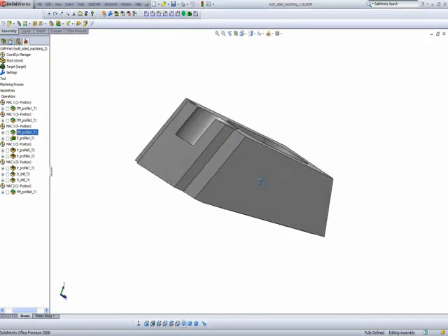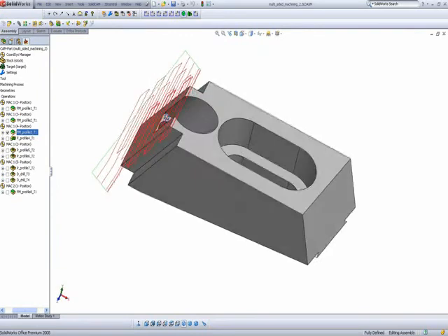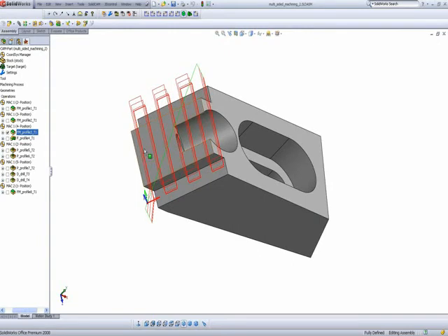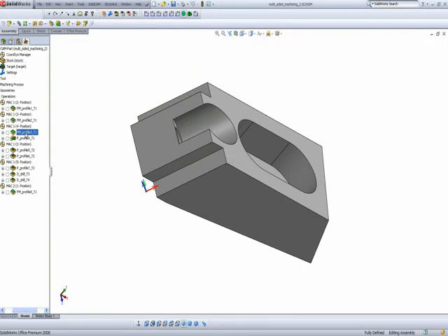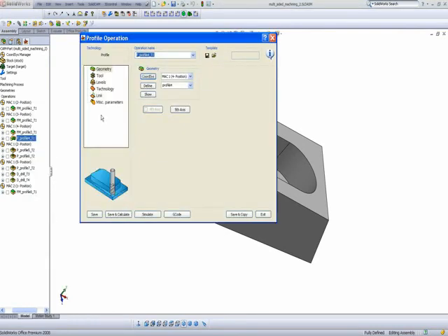Now in my next operation, I will be again doing a face mill operation, but on this side over here, as you can see. Again, I've used the MAC 1, however this time position 4, the fourth position. And again, I'm going on the surface back and forth using T1 with the same technology as I've used before. Now in my next operation, I want to continue working on position 4, but mill out these steps over here. I've simply done that by doing a profile operation.